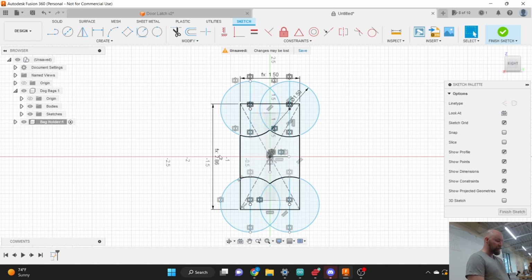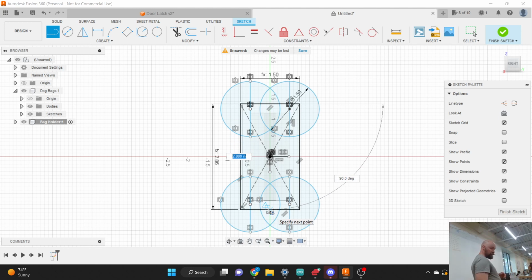I'm going to go ahead and say, actually, I'm going to divide my cylinder in half. So I'm just going to draw a line from the top midpoint of my cylinder down to the bottom midpoint. And you can see I'm getting the little blue triangle that pops up here, and that's what's telling me I'm snapping right to the middle.